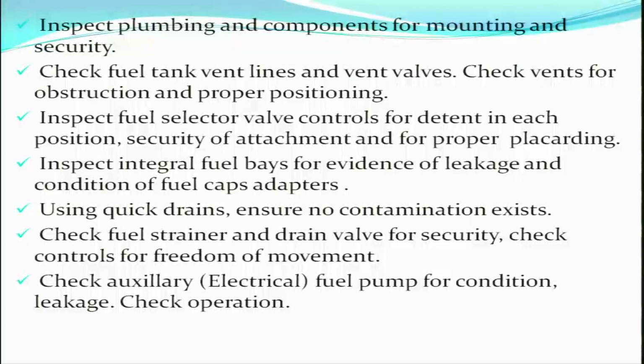Then comes your fuel selector valve. Inspect fuel selector valve controls for detent in each position, security of attachment and for proper placarding. So when you go on the aircraft, you will see that the fuel tank selector valve is there inside the cabin and you have the option of selecting the fuel from either of the tanks or from both the tanks. So you need to check the fuel selector controls for detent in each position and the security of attachment and proper placarding on the fuel selector valve.